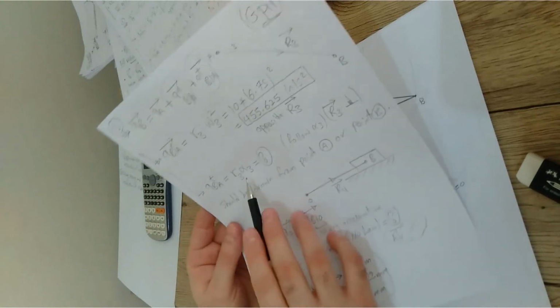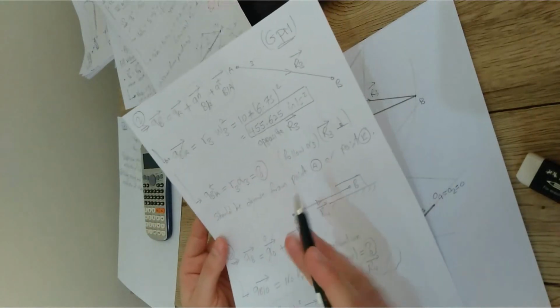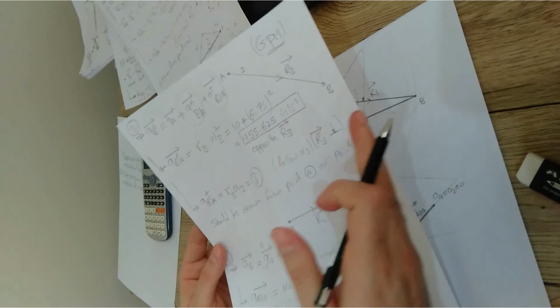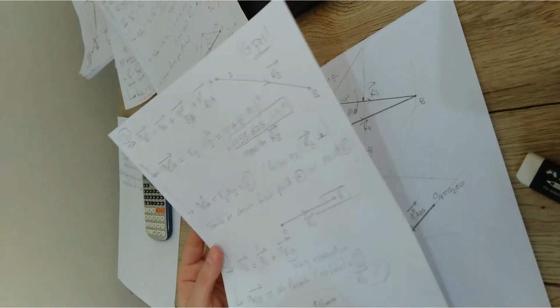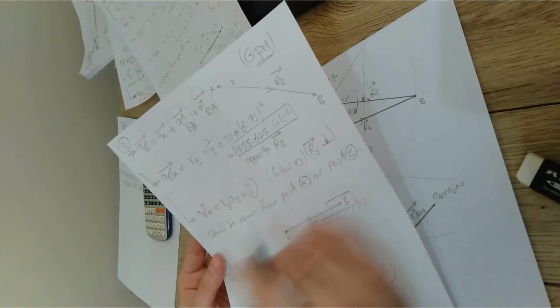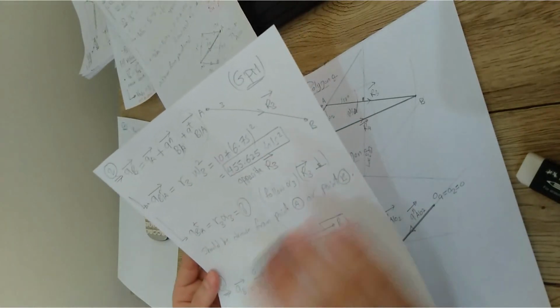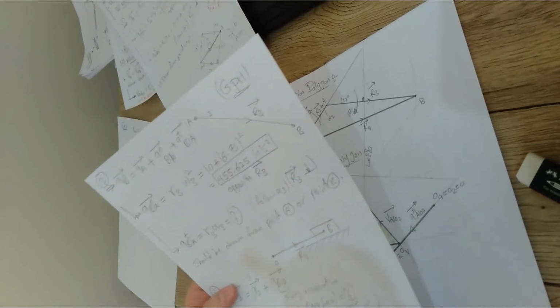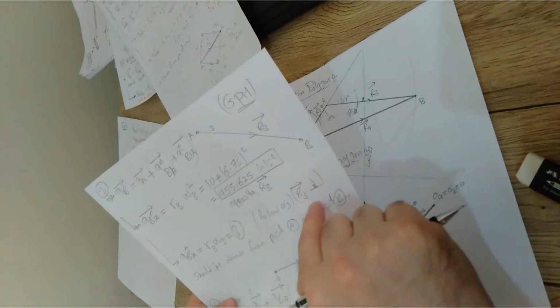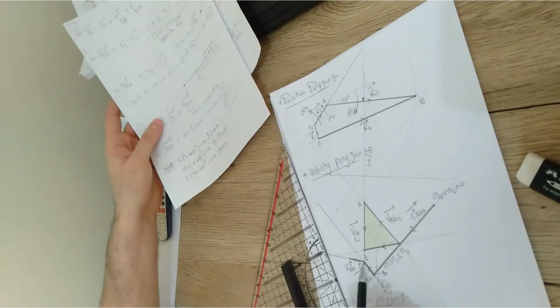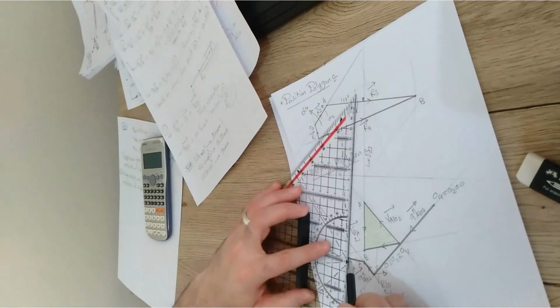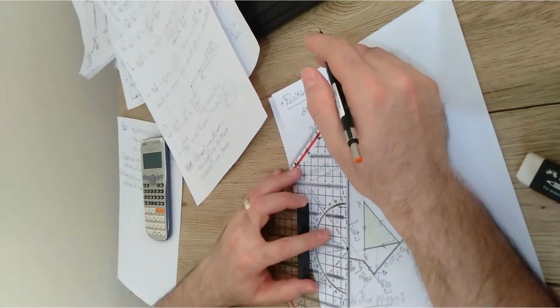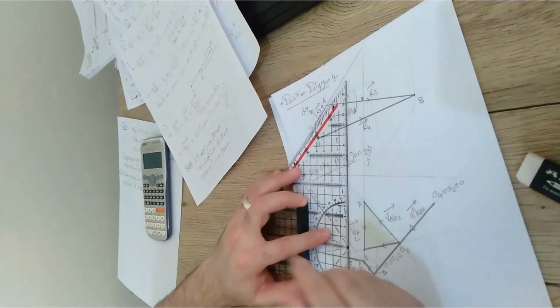Then you're gonna draw the tangential, but the tangential is unknown. But I know its direction, that it should be perpendicular to the R2, R3, but which direction exactly depends on alpha 2, which we don't know the value of alpha 2, even the direction, right, of alpha 3. So you have no option except just draw a line that is perpendicular to the R3 from the end point. I draw the normal from this point. You have to draw the tangential that it should be perpendicular. So simply perpendicular to the R3 should be perpendicular to the normal, the A normal itself.